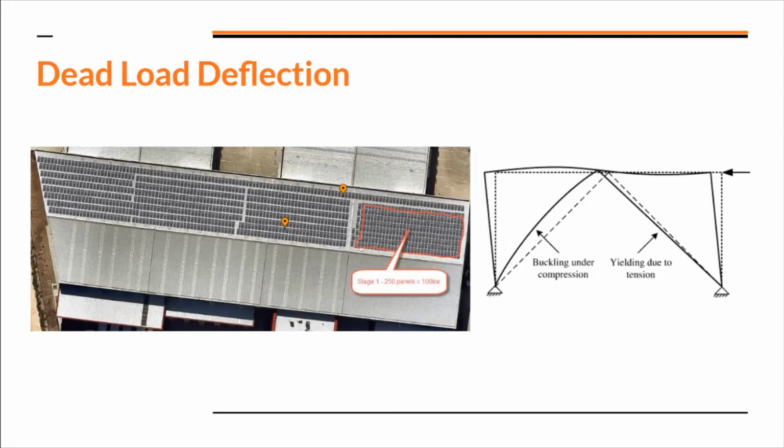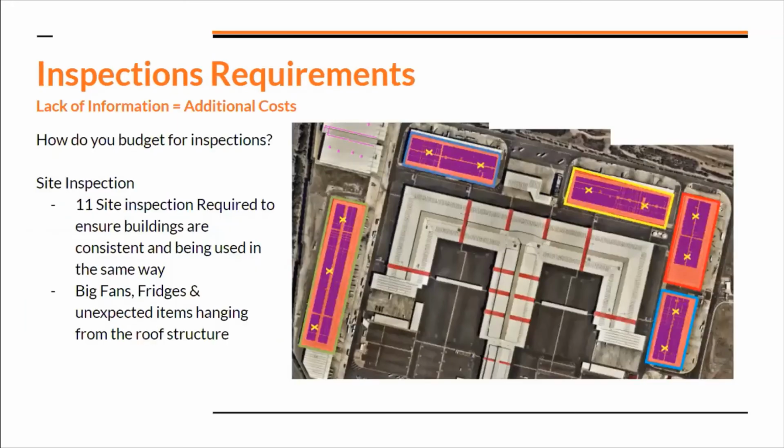So you need to start taking these considerations and say, hey, I know that guy on that presentation didn't remember much of what he said, but that north face can't be too overloaded. I could have put some on the south face as well. In regards to the structure assessment, it doesn't cost you any difference, because that rafter and purlin is going to be the same as that rafter and that purlin. So it's going to be more or less the same thing. Now, if you're tilting it and flushing it, then it becomes a different conversation. But in general, if you're just putting flush on both sides, it doesn't cost you any different, it's really just making sure that the building is now safe. Which is really a huge point that I want you guys to take out of this.